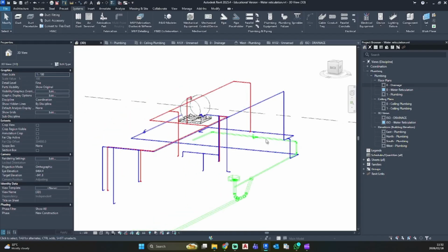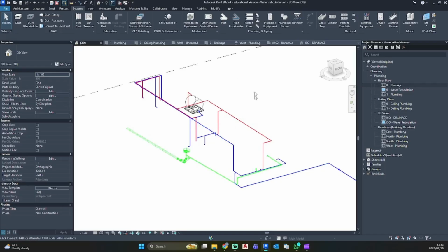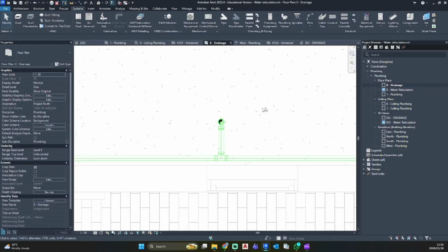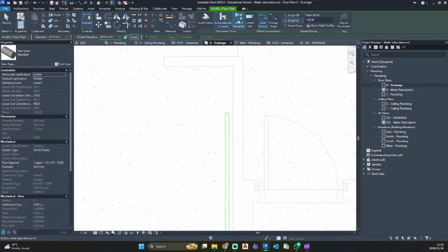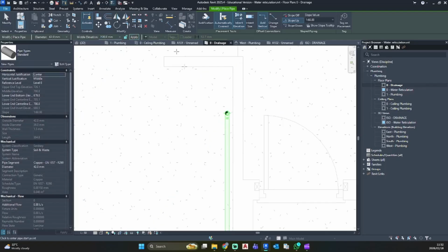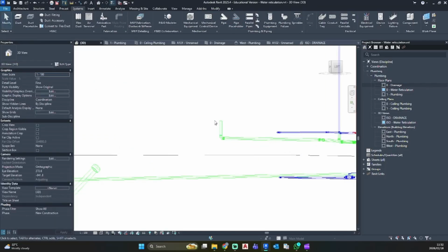It will be a lot easier if you load in your fixtures to work on it. I prefer, just for this video, to work like this to showcase how the systems will work with one another. So now we are going to do the same here. I'm going to create similar, inherit elevation, and I'm just going to click over here and go, let's go with 700 and apply. So there we have our dishwasher point or your laundry connection point.